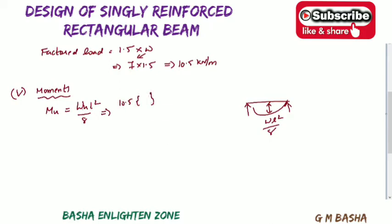And what about this here? We already calculated the effective length. Each and every time we use that effective length, so it is 3.162 whole square divided by 8. If you simplify this, you will definitely get around 13.1 kilonewton meter. So your Mu value will be equal to 13.1 kilonewton meter. Maybe some digits differ, 13.1 or 12.9, approximately 13.